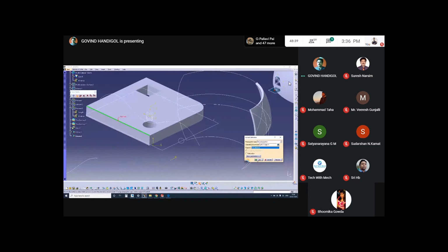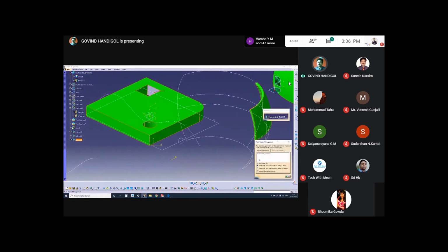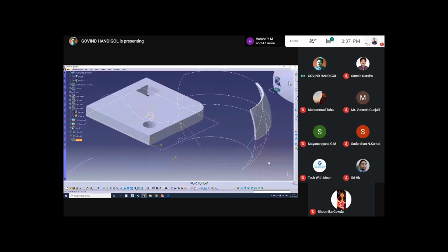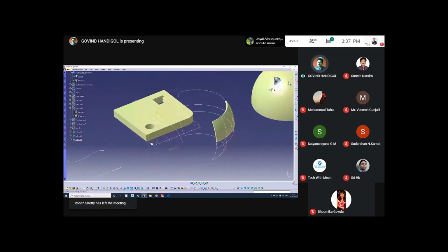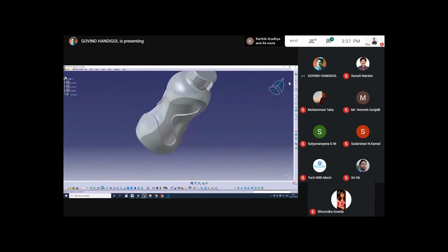Even though we can extract the curves, we can also extract the curves from the solid body. This. We can extract the surfaces. Again, this cylinder surface. This. Now the point continuity is different. Complementary means the opposite surface. The star surface you are going to extract here. All the surfaces. Like that. Extraction is done here. Like that. If I hide the solid, all surfaces are there. According to our requirement, these are some basic commands of the surface design.